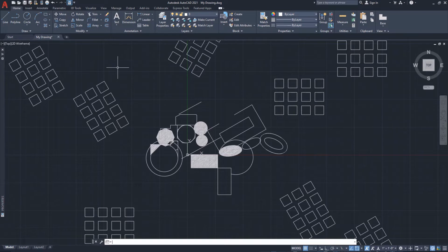Yet, at the end of the day, we need to show all of the important parts, pieces, and components of our design and model in a printed format. In this printed format, these objects are displayed at some specific drawing scale factor. Not only do annotations need to be legible and of proper size on the printed page, but they also need to be legible and of a proper size in the model space drawing environment. Annotative scaling is a tool or mechanism that manages the proper display of our drawing annotations.